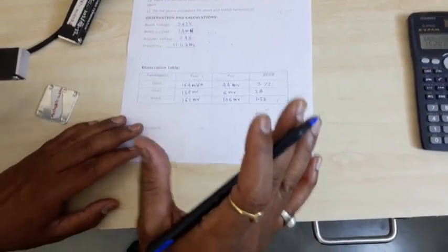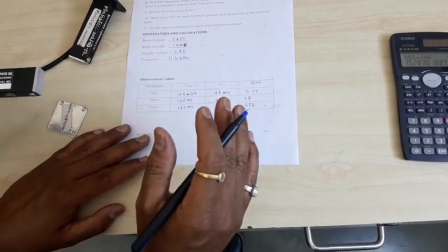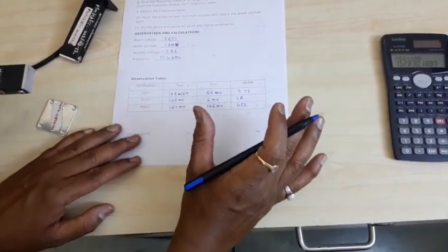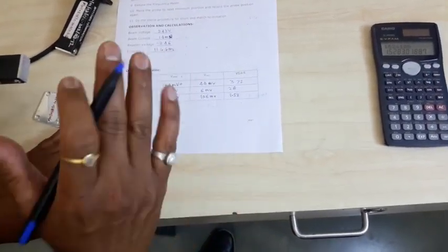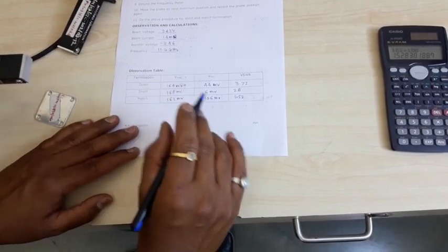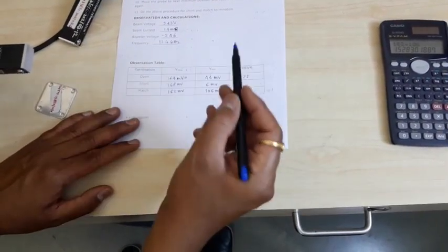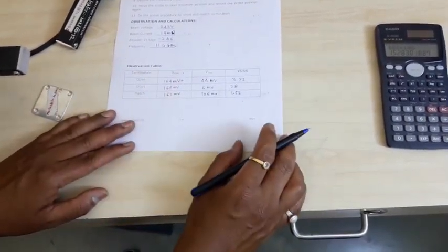In industrial applications, the maximum VSWR that can be considered is 2. Between 1 and 2 can be acceptable. If VSWR goes beyond 2, it means there is a mismatch and there can be reflection towards the source, which cannot be accepted.